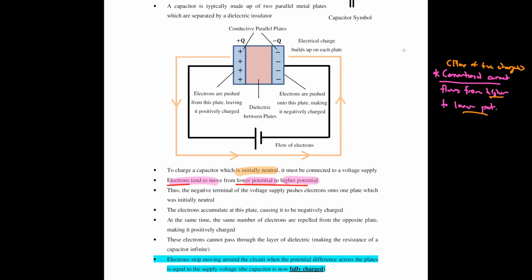So right now, if you look at your diagram, if I were to tell you that this cell or battery has a PD across it of 12 volts, I could probably imagine that this potential here and this potential here could possibly be 6 volts and negative 6 volts respectively, so that the difference between them gives me 12 volts.